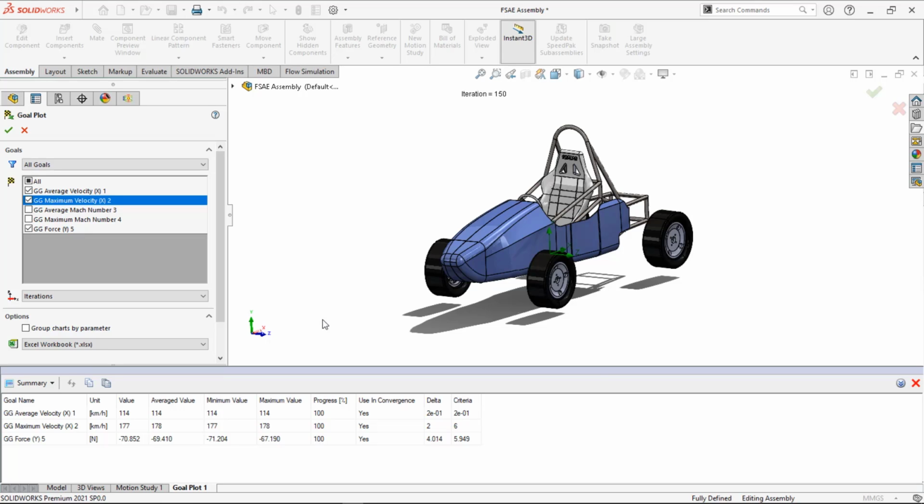Yeah. So now what I'll do is, to get the drag force to approximately 500 Newton, I'll try to include a few more structures into the model so that I can achieve the 500 Newton drag force according to the reference papers and the case studies. That is around 450 to 550 Newton. So for that, I'll just create a new configuration.